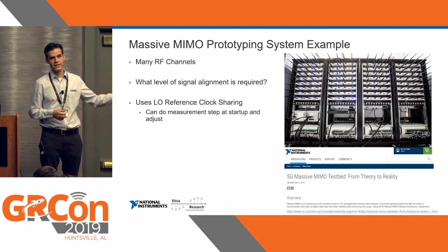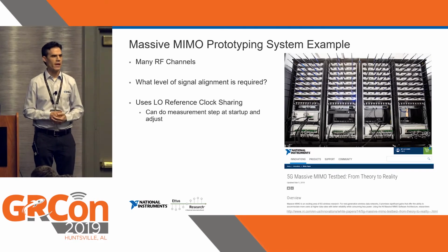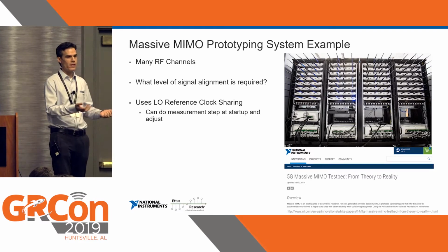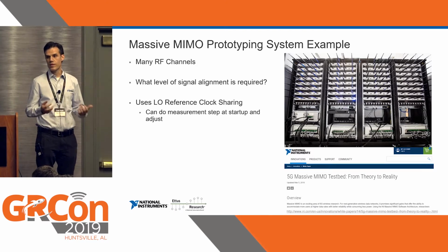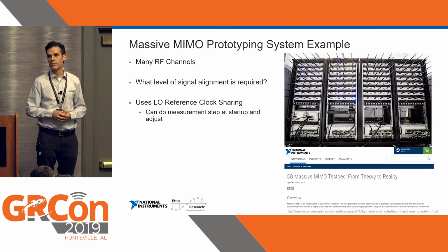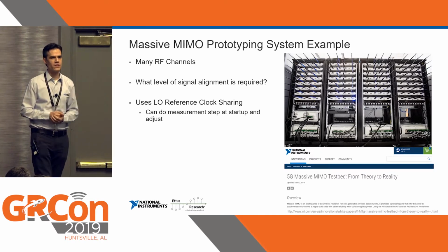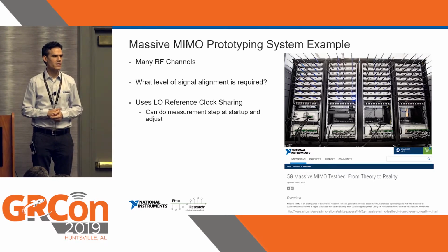One example of that is this massive MIMO system that we put together many years ago as people were trying to research what massive MIMO could be. At that point in time, it was just theoretical. Running MATLAB sims is one thing, but if you can actually do an end-to-end link and prove that it works, that's something else entirely different. We were able to use existing X310s. Here you see 4 racks that have 128 channels of X310s.